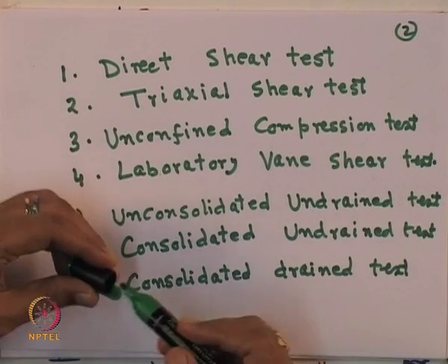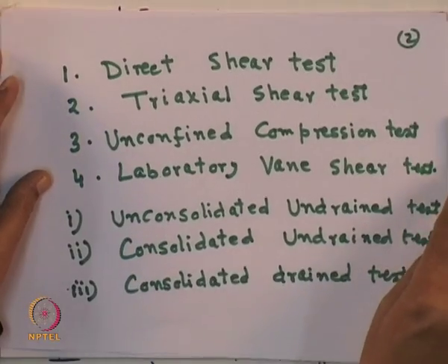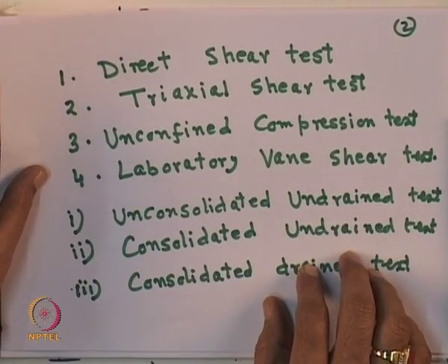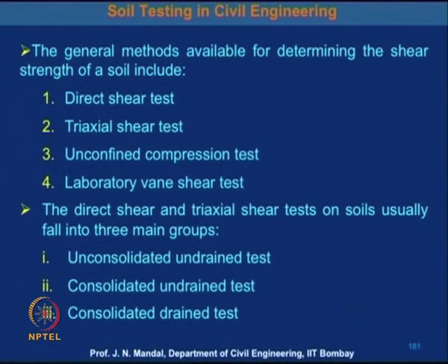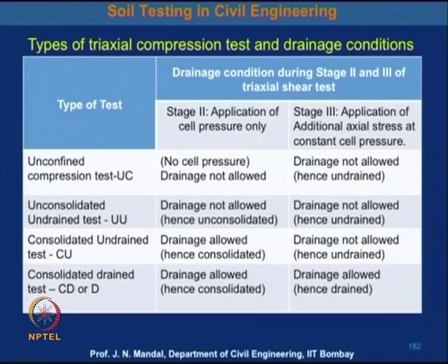Now, the type of triaxial compression test depends on the drainage condition. This is very important, what the drainage condition should be. First of all, you prepare the soil sample and then you apply the load.